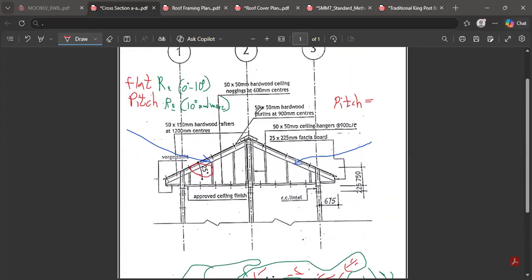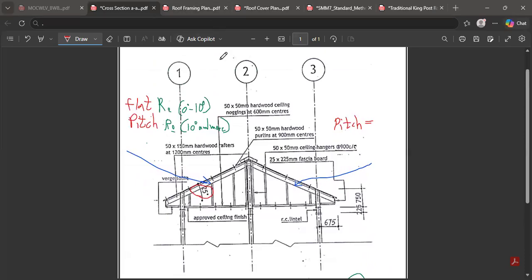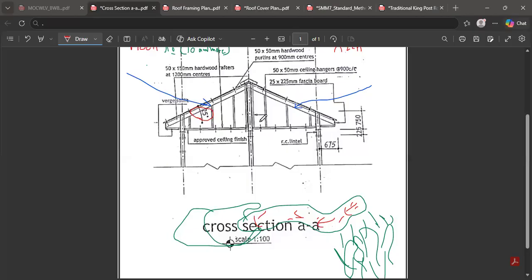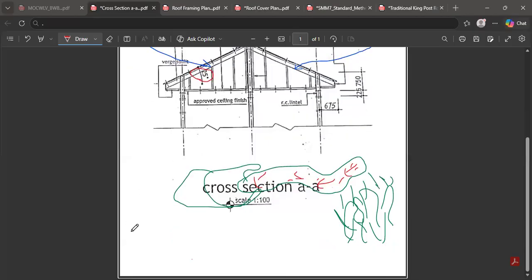All right, let's proceed. So I said I wanted us to solve some questions. I'm saying that I want us to start solving some questions now. Okay. Right away from here, I want to tell you that roof members are measured in meters, just as I told you. That is the linear meters, okay? And the members of the roofs that we are going to be focusing on in this calculation are the rafters and also the purlins, okay?